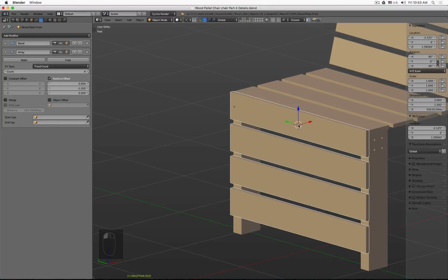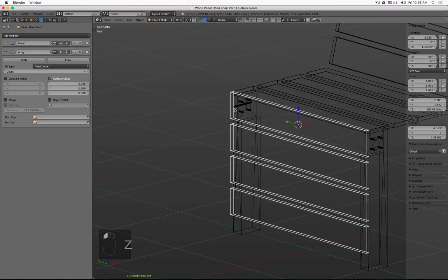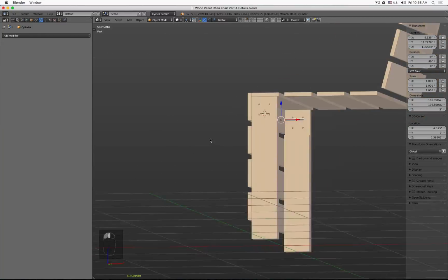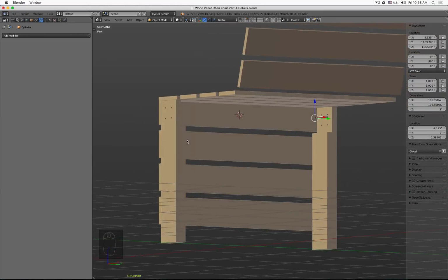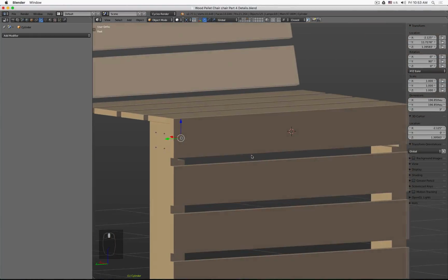So you see I positioned my 3D cursor at this plank because this is actually the midpoint. Then there I created the cylinder, and then I moved it over and used the position of this lumber part to figure out where I have to position this one. Then also here I can do a check, so this maybe does not interfere with the rest, and it doesn't.